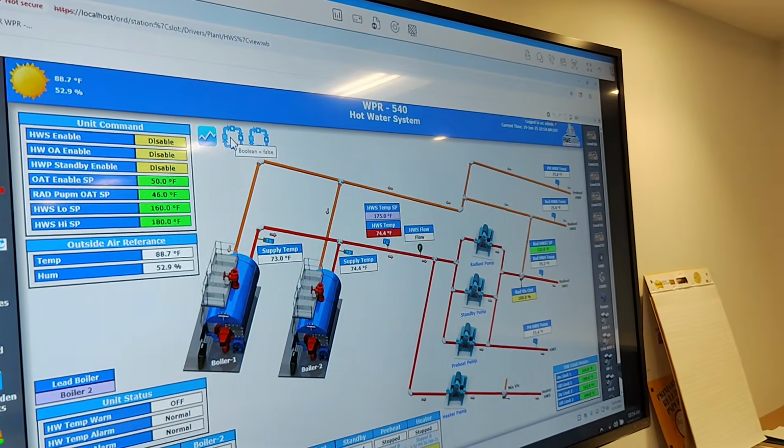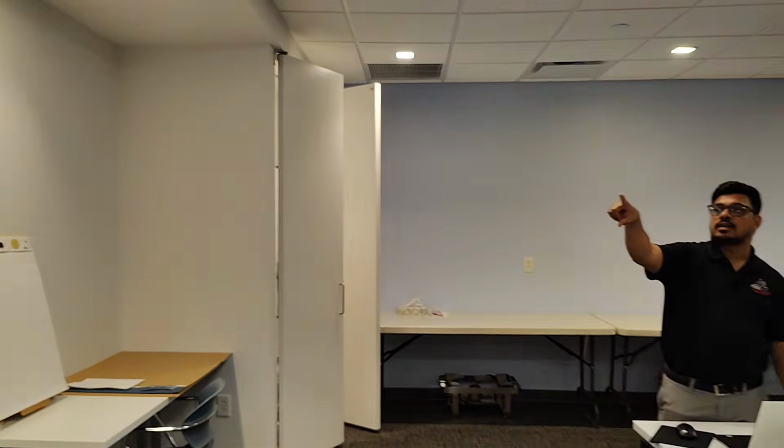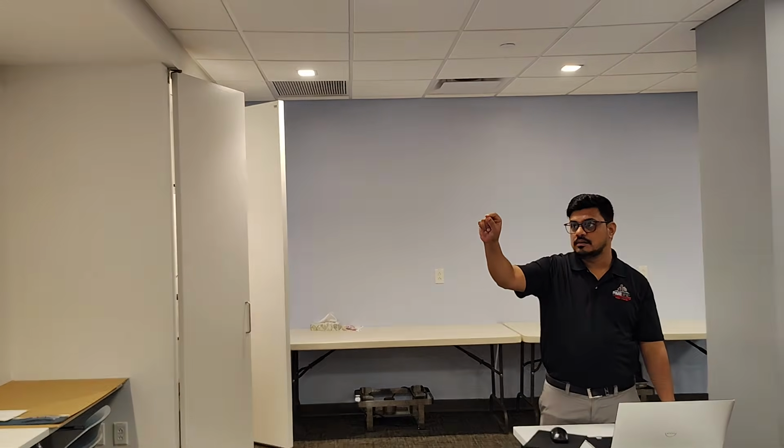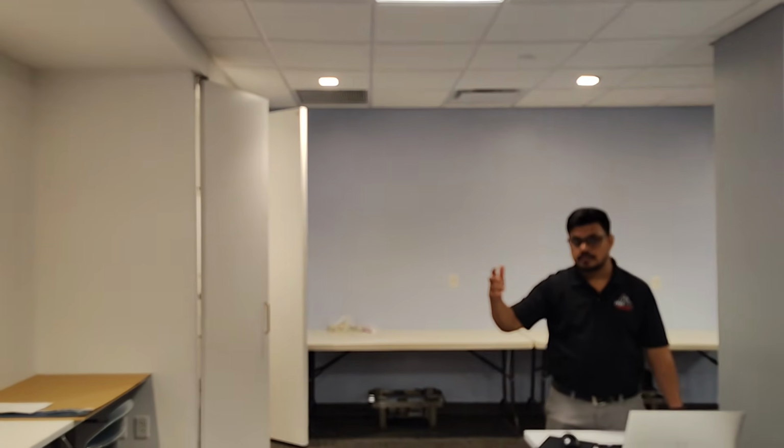This shows if your controller is online or offline. That blinking white dot goes to red if your controller is down. It is not communicating online with the supervisor, which you have provided on the BACnet. But now it's connected.